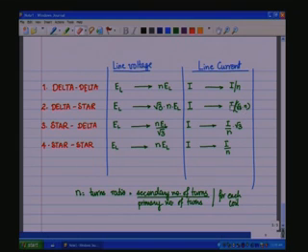The phase current in the case of the delta star is going to be I by root 3 n, but on the primary side the phase coils will be rated at I by root 3 rather than I, and therefore the primary side phase coils can have a smaller gauge. So, one could specifically argue along these lines and suitably rate and pick the proper topology of the transformer for a particular application.